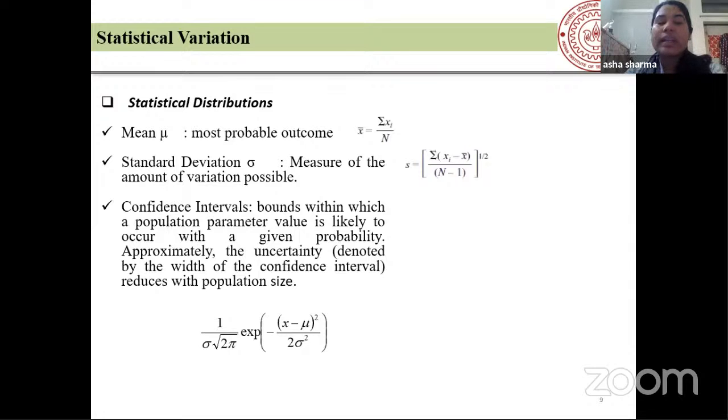And as I told you, the statistical distributions are actually Gaussian distributions. So we can define the Gaussian distribution according to this formula. As we have calculated our mu and our sigma, we can calculate the probability of the breakdown of the particular insulation unit.